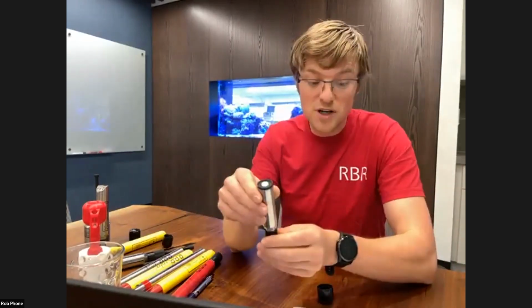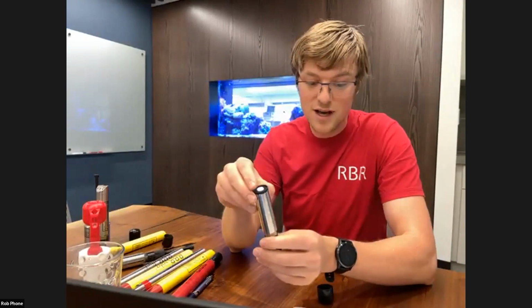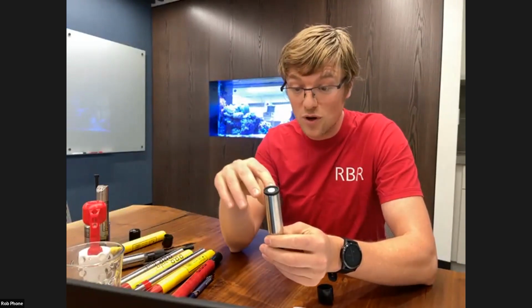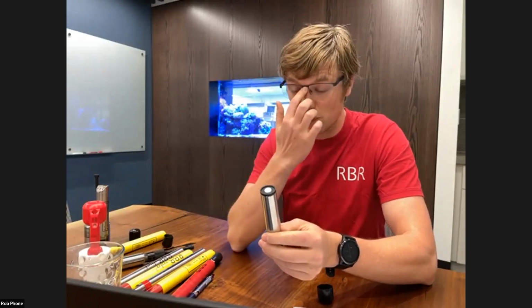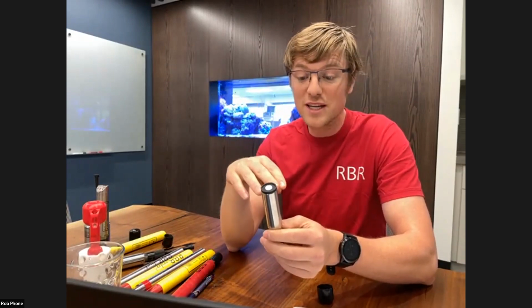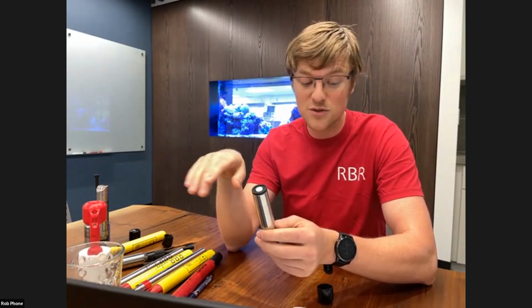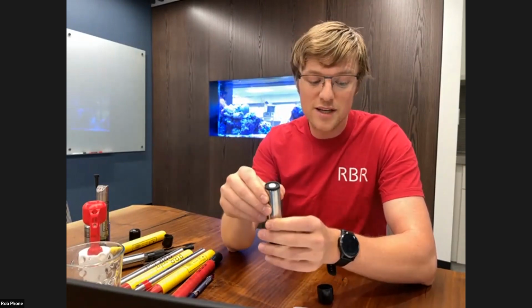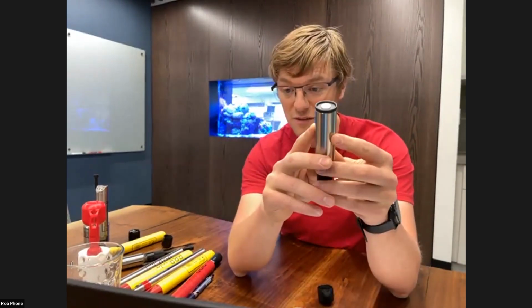The spectral response is obtained by the selection of components for the sensor. So ensuring you have a high quality filter to select just for the particular wavelength you want and has a high out of band rejection, and also making sure that you have a good photodiode that has a nice flat response across the region that you're interested in. The cosine response is driven by the construction of the face here.